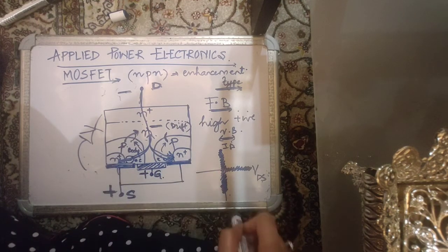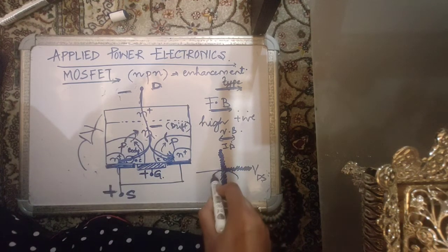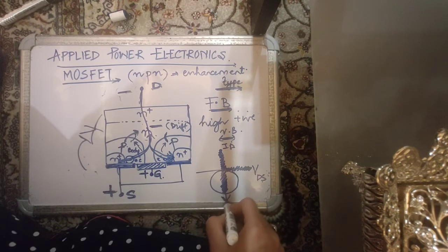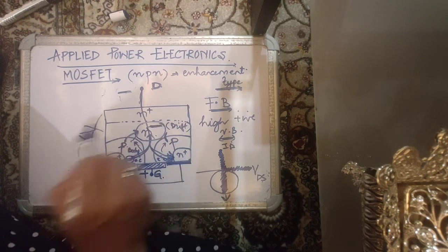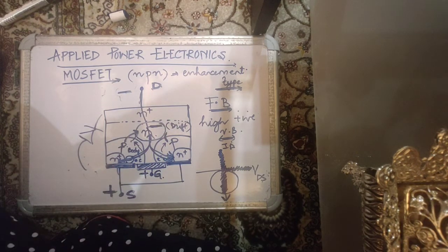But I also told you in the first lecture that it is generally not used to carry negative currents, because if you see, this body diode has to carry current through the N minus region. The N minus region has fewer carriers, and when it has fewer carriers, its on-state resistance is high, as a result of which it is a lossy path for the current to go through. When it has to take the reverse direction through the body diode, it will produce more drop.